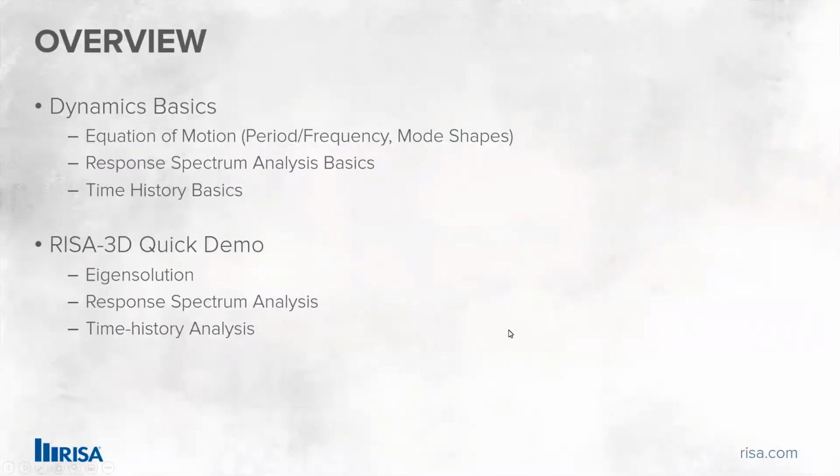Now in today's presentation, here is an overview. I wanted to first talk about some dynamic basic knowledge in terms of what is the equation for motions, period, frequency, mode shape. And also I wanted to talk a little bit about how to perform a response spectrum analysis and a time history analysis. Those are some basics of dynamics that I would like to refresh your memory for your dynamic classes in college. I'm not here trying to teach you dynamics because it's a very limited time. So I just wanted to refresh your memory so you can catch up the parts that when I do my demo, you will know what I'm talking about.